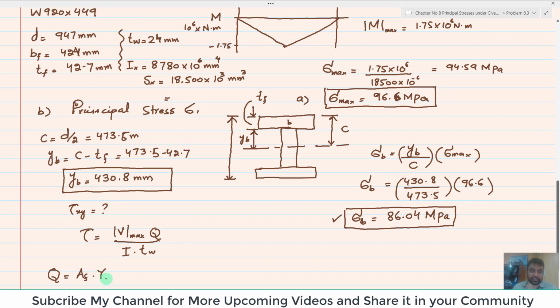YF dash. Now what is AF? So AF is equal to area of flange, which is breadth of flange multiplied by thickness of flange. So BF into TF. When you multiply both values, it will give you 86.1 into 10 to the power minus 6 cubic meter. Clear?